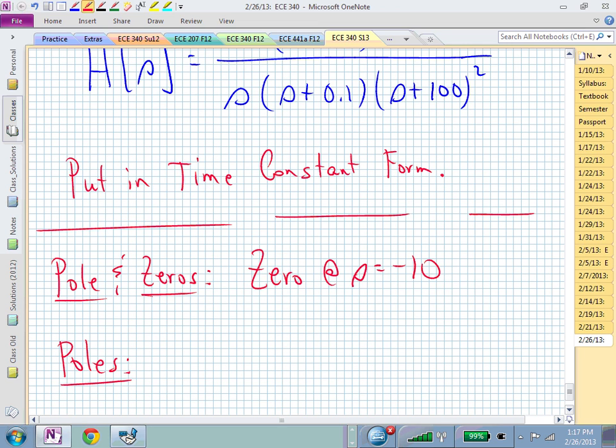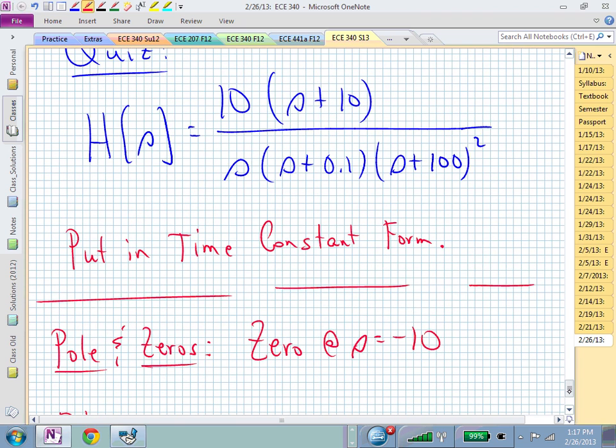What's the order of this system? And how much of that transfer function do I need to show you? Could I have gone ahead and scrolled up? As long as you know the numerator order is strictly less than the denominator, that's a strictly proper transfer function.